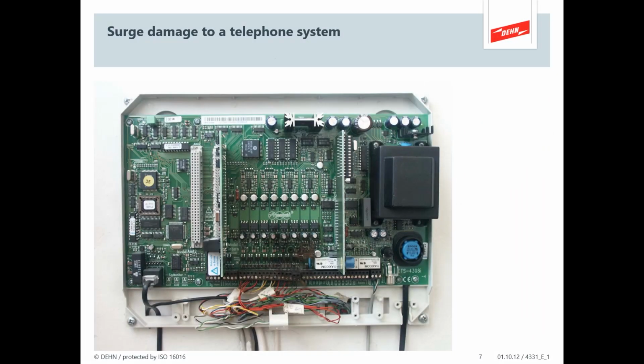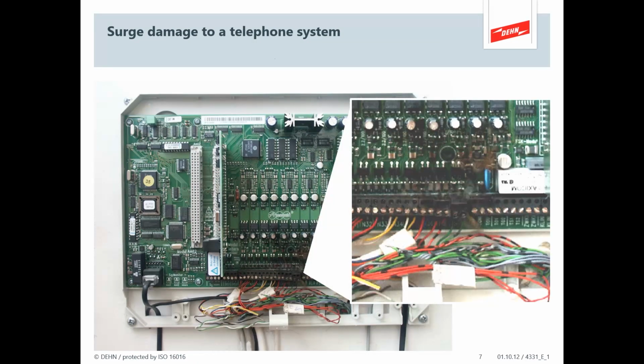And here we can see a slightly larger telephone system. Now, this is typical of, say, a small business or a retail unit, something like that. And we can see just about that there has been some damage. We can see the printed circuit board is blown to bits. Where the cables come in, that's looking very charred. Now, this business is going to be offline. The cost of replacing this unit may not be a huge amount, but it's the downtime. That's what's really going to cost the money. And this is what you have to factor in when you decide, yep, I'm going to have SPDs or not. It's not just the physical thing that you're replacing. You have to think about the disruption to the service as well.